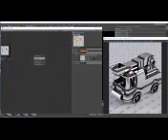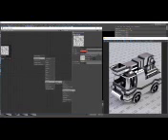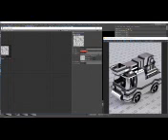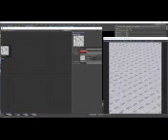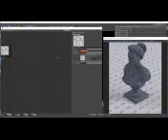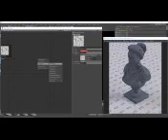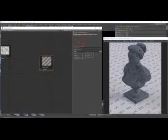We also used the Corona Triplanar on a few occasions previously, but due to its importance, let's briefly take a look at it as well. For now, let's hide the truck and unhide the sculpture model. Assign a new Corona material to the model and load a Corona Triplanar texture.